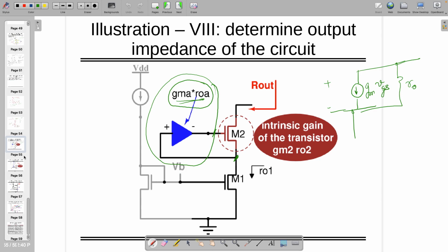Are you following what I'm saying? What I'm doing? So the technique I am doing is this source potential is actually getting multiplied with some amplifier. I'm keeping it here in the loop, and that is what actually tunes the gate voltage of M2. It's actually improving VGS overall, right?